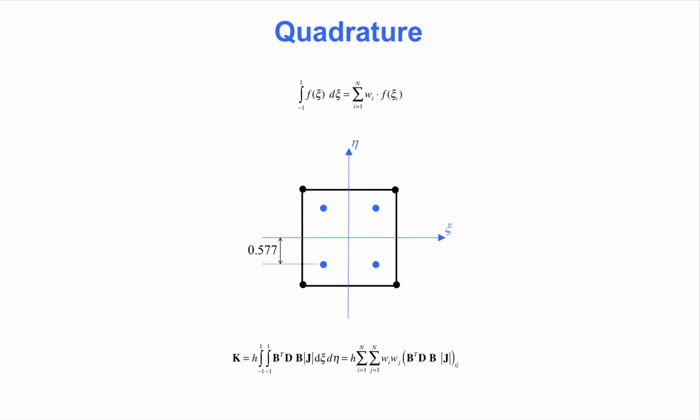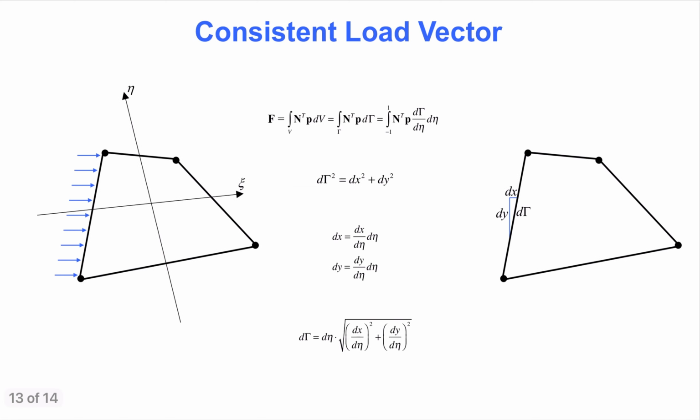The final slide addresses the load vector. It is only for some elements that it is possible to lump distributed element loads as concentrated nodal loads according to tributary areas. In general, we must evaluate an integral, giving what we call the consistent load vector.